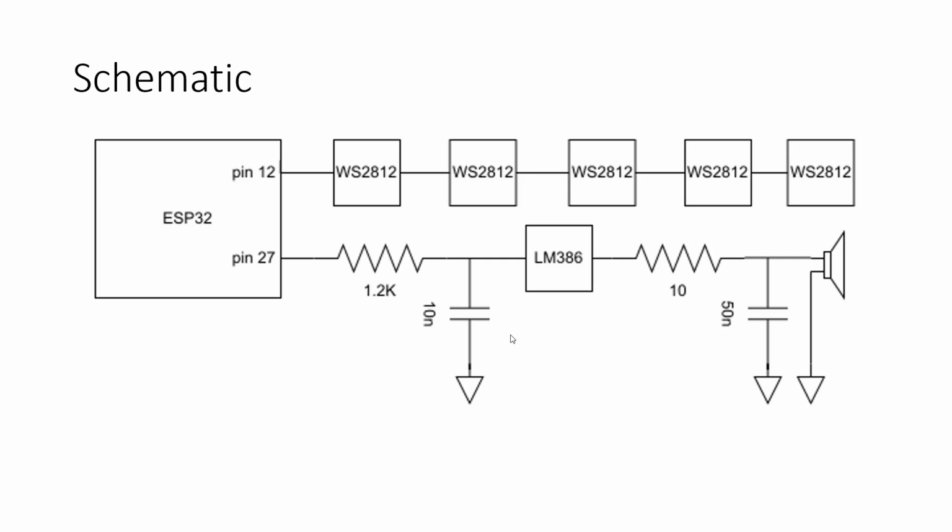According to the data sheet, it was for stability of the op amps. Yeah. It was dictated to do in the data sheet, but we don't understand the concept behind it, right? But basically that connects to the speaker, and the speaker's on the board, right? So in principle, this should allow us to convert a PWM signal to an audio coming out of the speaker, right?